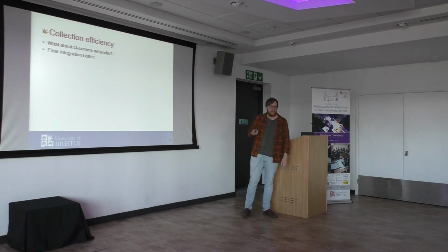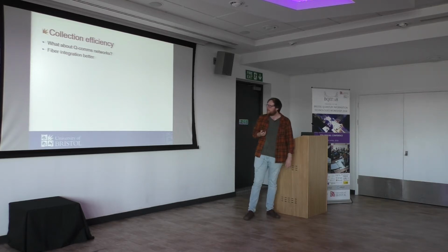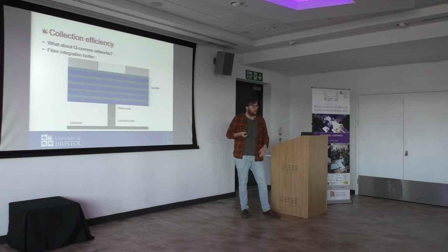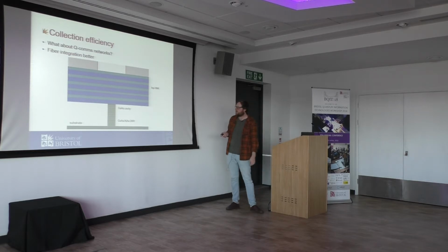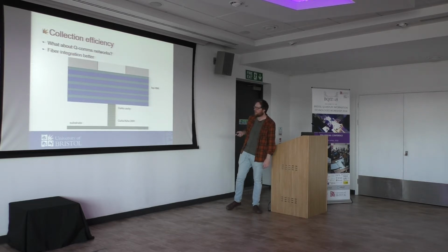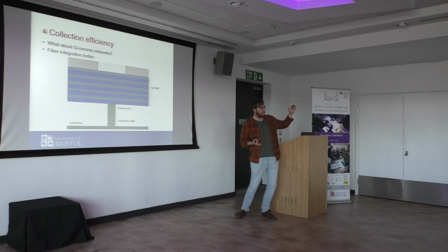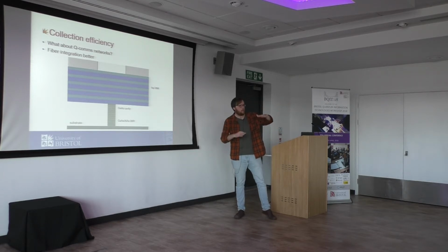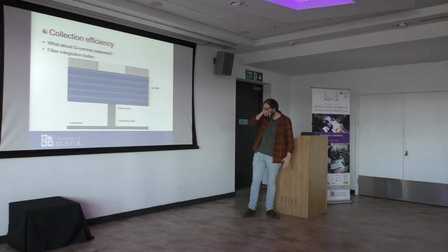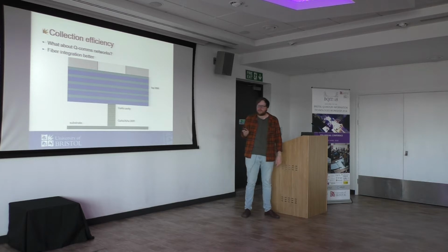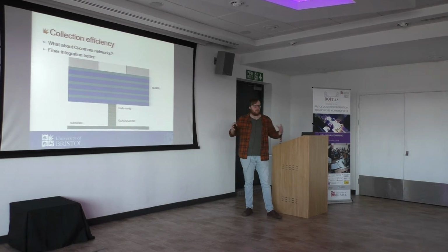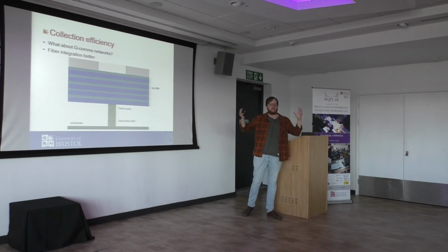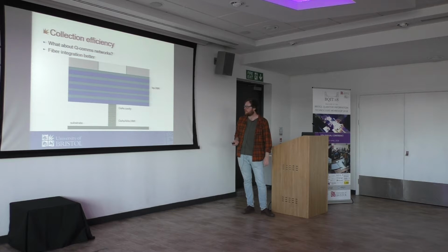One of the many approaches that we've been pursuing in Bristol is really co-designing the photonic structure and the output of the device. In this example, we've got a gallium arsenide half pillar, and we complete the cavity by having a fiber that's got the mirror coated onto the fiber. This is still very much in its early stages. I don't have anything quantitative to say about it at this stage, but this is the sort of thing that we're thinking about in terms of really increasing the overall efficiency of these quantum dot-based technologies.